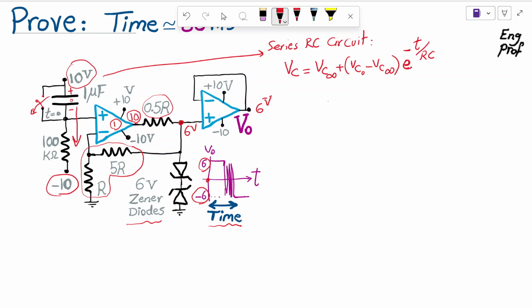Okay, so what is the benefit of this? Well, think about it this way. At time 0, the voltage of the cap is 0 volts, because the switch was closed and it didn't allow the cap to accumulate any voltage. At infinity, if you let the circuit charge up the cap after you open the switch, at the end, the plus minus 10 volts will appear across the cap. The resistor will be nothing. So at infinity, you have 20 volts across the cap. 20 volts here as well.